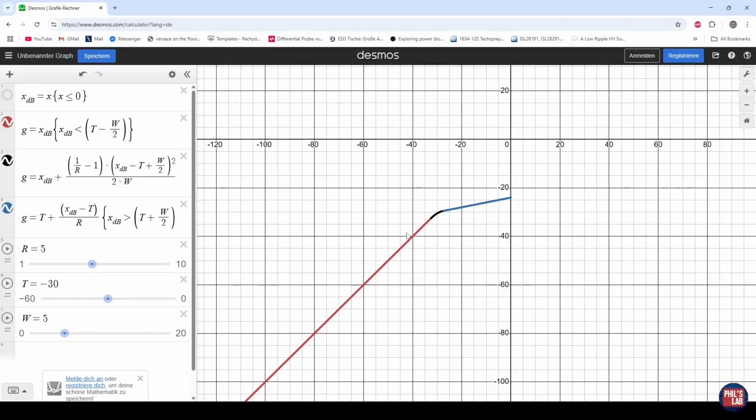This is what's known again as a soft knee, and I can change the knee width, which is indicated by W on the left-hand side. So I can increase my knee width, and you can see that black region, that transition region, is now expanding and giving us a softer transition. If I change my knee width down to 0, you can see this is now a hard knee. It is a single point transition. Oftentimes, compressors are favored with soft knees, and that's what we'll be implementing, but you can implement a soft knee and simply set your knee width to 0 to give yourself a hard knee. And of course, this changes the sonic characteristics and might be less aggressive of a compression.